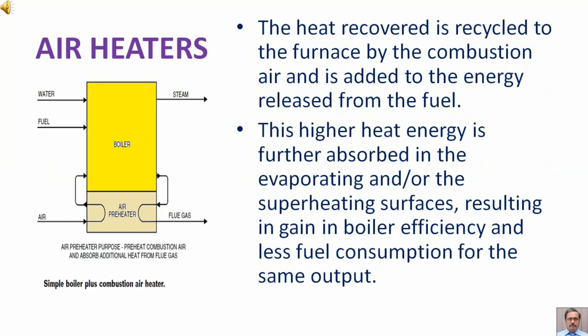The heat recovered is recycled to the furnace by the combustion air and is added to the energy released from the fuel. This higher heat energy is further absorbed in evaporating and or the superheating surfaces, resulting in gain in boiler efficiency and less fuel consumption for the same output.